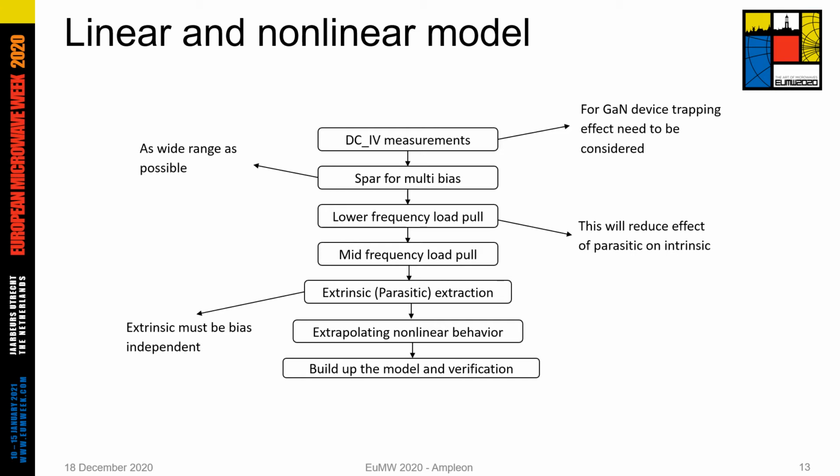Then low frequency, low pull. What I mean by low frequency is that the frequency needs to go so low that the parasitics or extrinsics will not play a role, and then you can really see the non-linearity at the core of the device at the lower frequency.